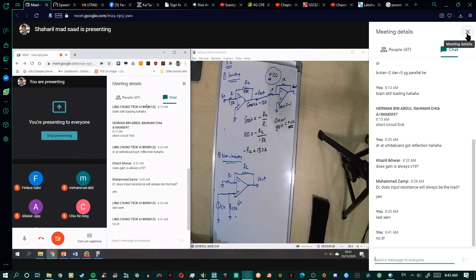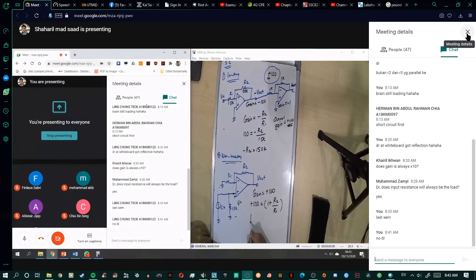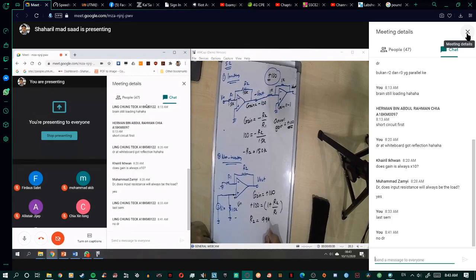Now you want to get the gain of plus 100. That means 1 plus R2 divided by R1. So let's say we choose R2 is 99k and R1 we choose is 1k. So 99k divided by 1k, you get 99 plus 1, then you get 100. So when you draw the circuit, this is 99k and this one 1k. Now when you use the non-inverting, yes, you can get positive 100.